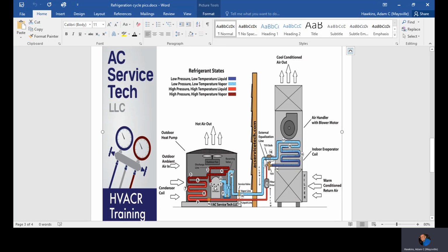You've also got a compressor. That compressor is taking in refrigerant, compressing it like an air compressor would do to air, building its pressure, and then creating flow. So that's the heart of the system. That's the thing that's pumping. That's the thing that's moving refrigerant. So without the compressor, you've got nothing. When your system's sitting there dead, nothing's working, you're going to be at what we call standing pressure, which is just lines full of refrigerant.